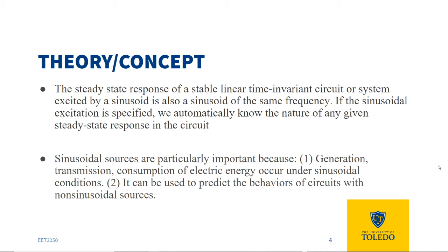Theory and concept. The steady state response of a stable, linear, time-invariant circuit or system excited by a sinusoid is also a sinusoid of the same frequency. If the sinusoidal excitation is specified, we automatically know the nature of any given steady state response in the circuit. Sinusoidal sources are particularly important because, 1, generation, transmission, and consumption of electric energy occur under sinusoidal conditions, and 2, they can be used to predict the behaviors of circuits with non-sinusoidal sources.